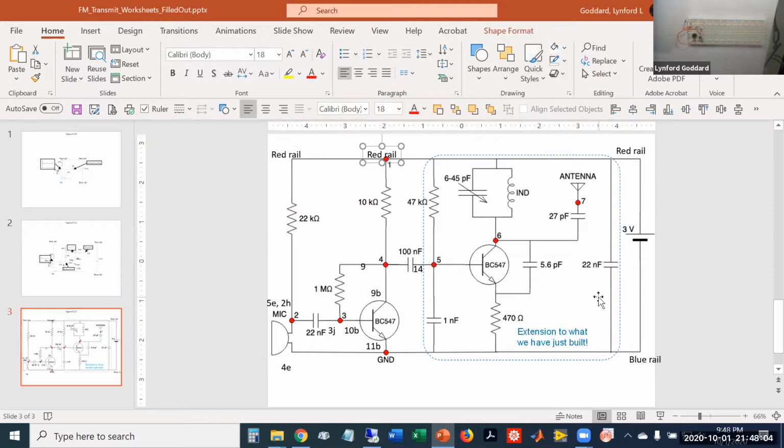And so I mentioned that it's good to lay out the transistor because this is one of the elements that we have to be careful about which leads we use. There's a few elements before it. So these are probably going to be roughly column 15 or so. So I'm going to put this transistor closer to 18 on the circuit board.